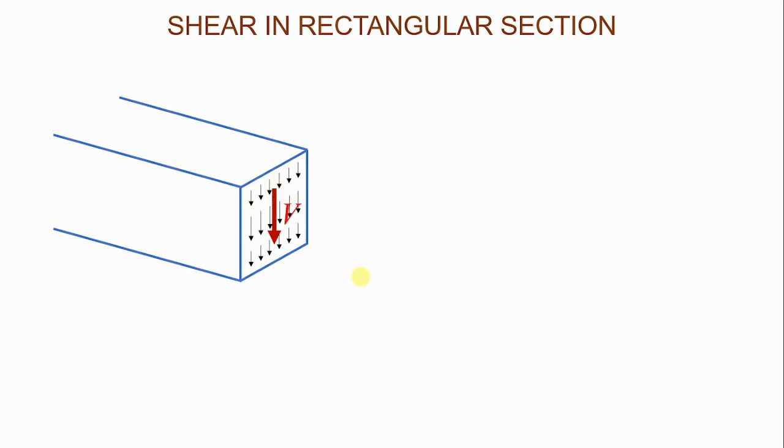That's really important. When we were doing Strength N5, we learned that the equation for the shear stress is equal to the shear force divided by the area that is in shear, okay? But that equation is a general equation, and it will give you the average shear stress on the section, okay? It's going to give you an average value for the shear stress on the section. But in this module, we will begin to find specific values for the shear stress at specific locations on the section, okay?